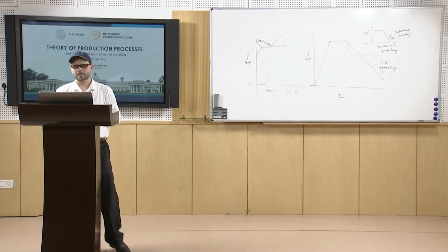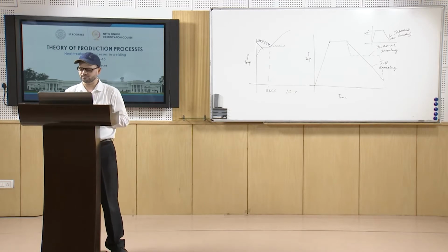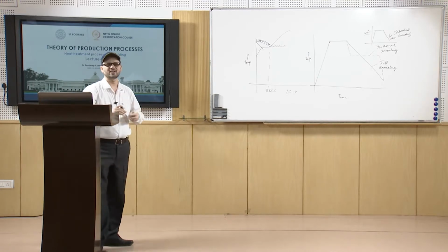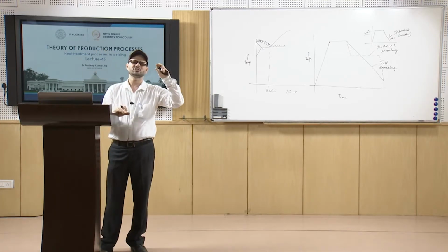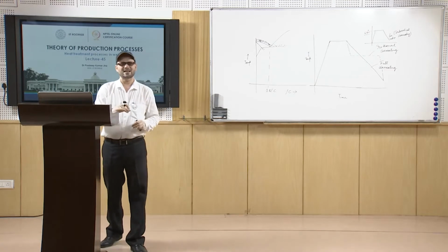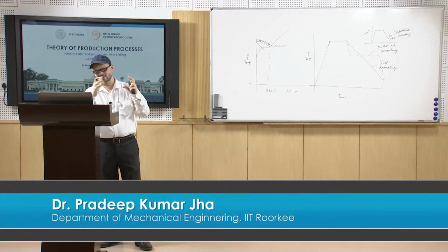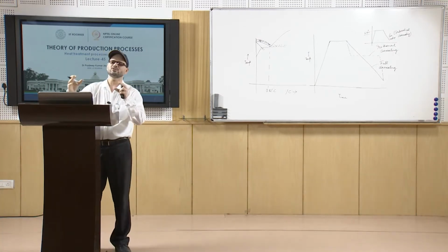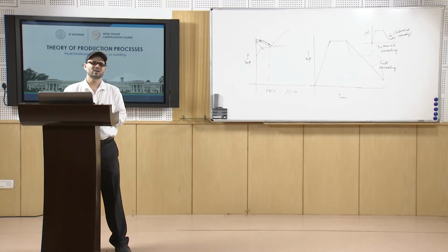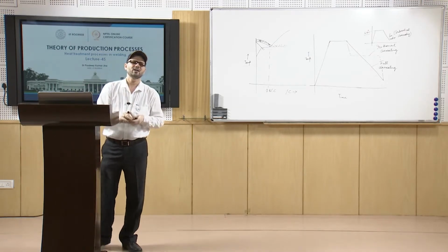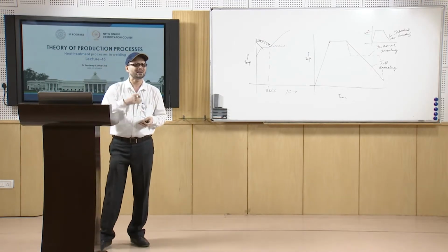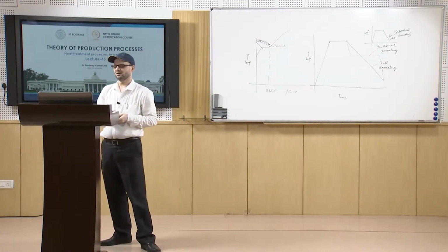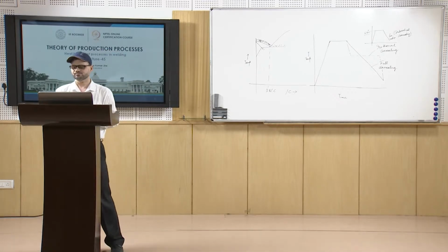This way the spheroidization treatment is employed, and in that the cementite which is in the lamellar structure, once you have a good amount of time available and you are holding it for some time, you get spherical cementite particles. We have already discussed that while discussing the heat affected zone in the earlier lectures.